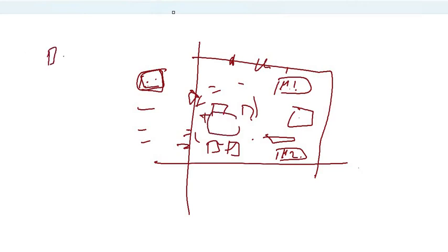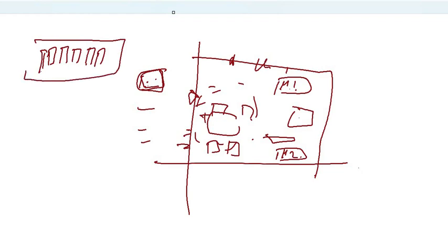Say if you've got current mirrors, you would place all the transistors here, with the dummies and the guard ring as well. Another very important thing is that whenever you're doing a placement, you should place the devices in a particular matching pattern along with the dummies and the guard ring. Only then would you get a correct estimate of the area this current mirror is taking. You might just end up arranging the four devices, sharing the sources and drains, and you would end up shrinking your module just to show that you have completed the module in such a small area.